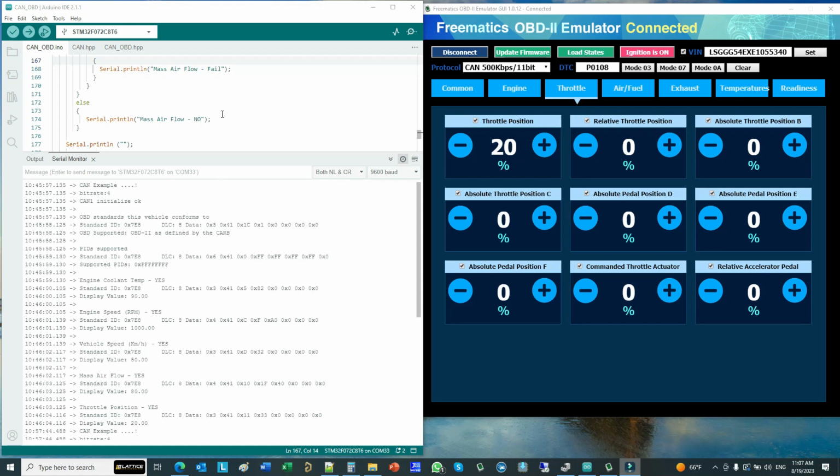In this video, I'm going to explain how the CAN adapter works. The CAN adapter is a USB dongle or stick with a CAN transceiver and CAN MAC layer. It can be used for car and vehicle applications like OBD, or onboard vehicle diagnostics, to query the car for different data like the vehicle speed, the engine RPM, the temperature, and so on. So we are going to apply this today and see how it works.